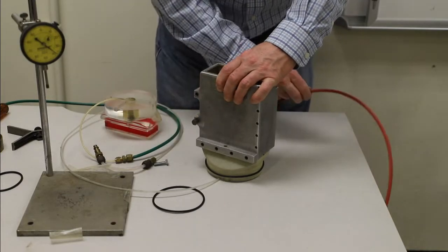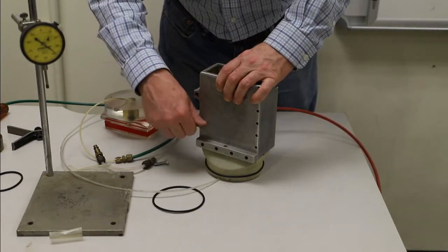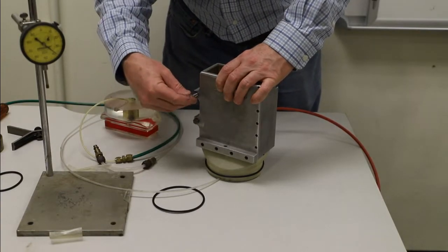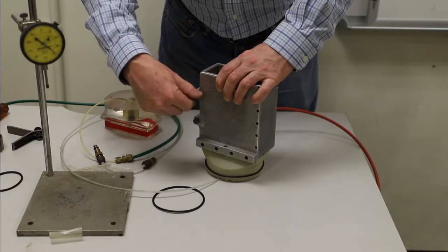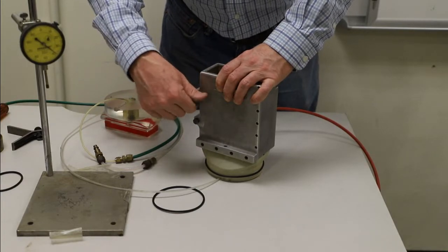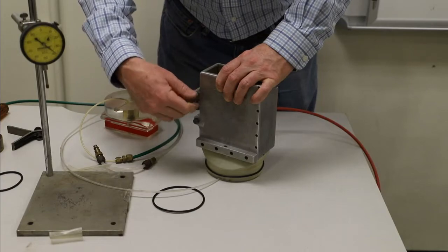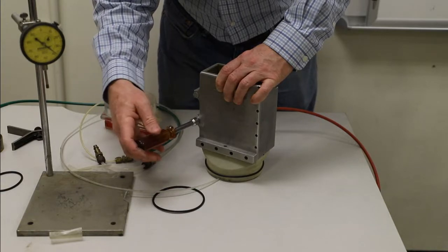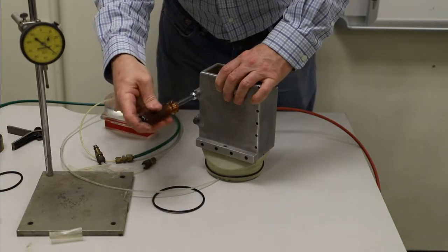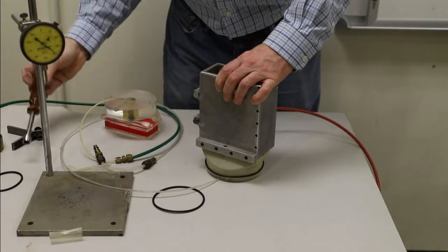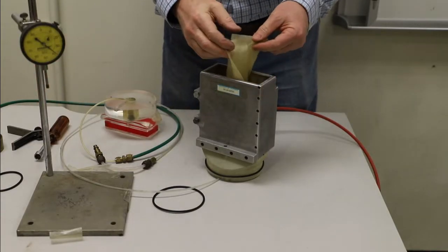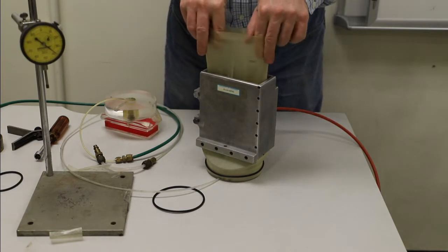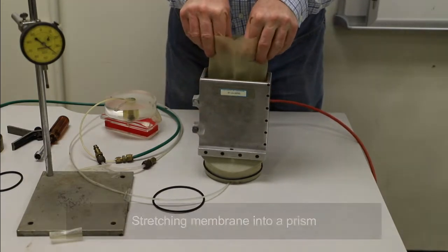But again, this red line is a drain line or a vacuum line to the mold. So again, the mold is lined with a porous material. So when we apply vacuum to that inner surface, the vacuum can pull the membrane up tight into a regular rectangular prism, right? We don't want a specimen that's varying in cross section. That would make the data interpretation very confusing.